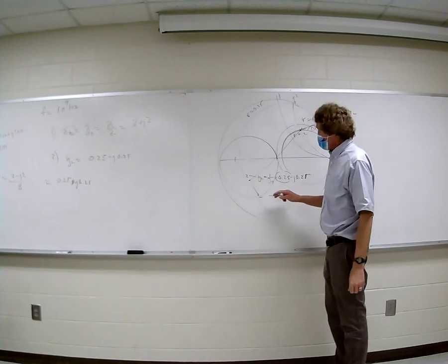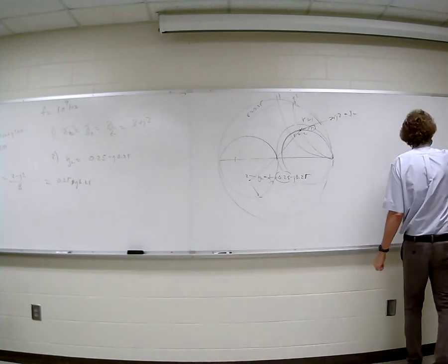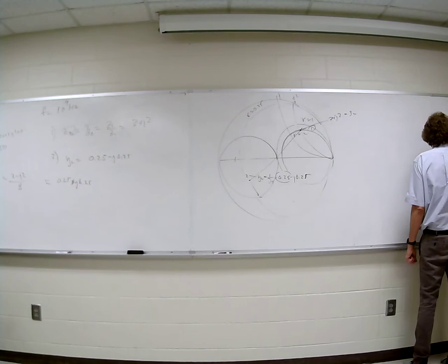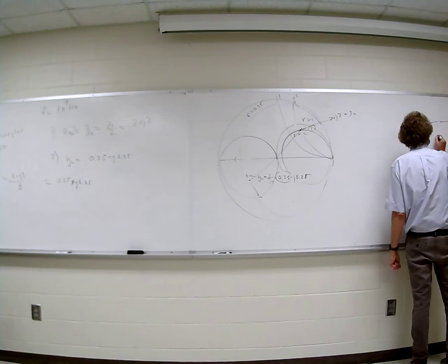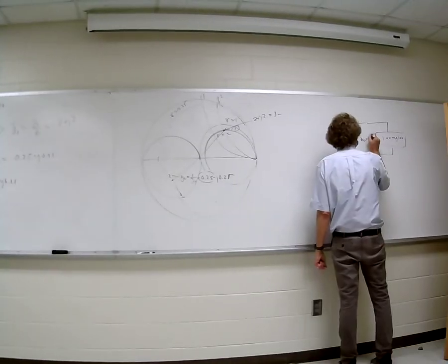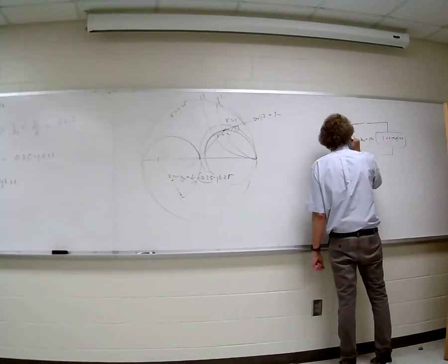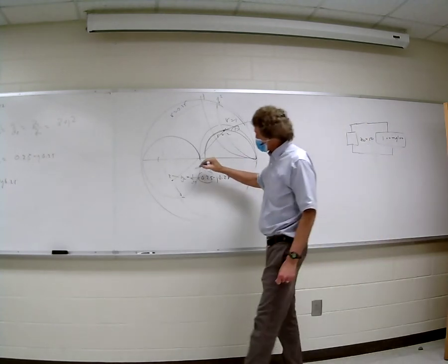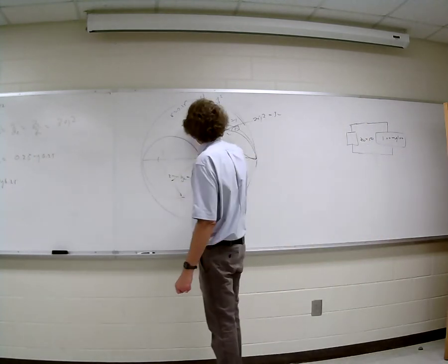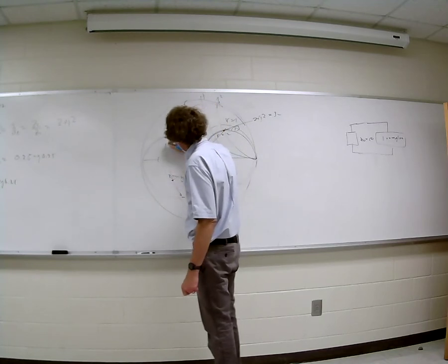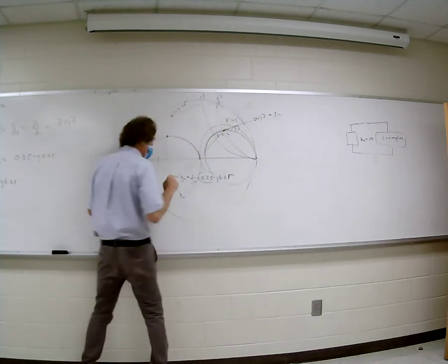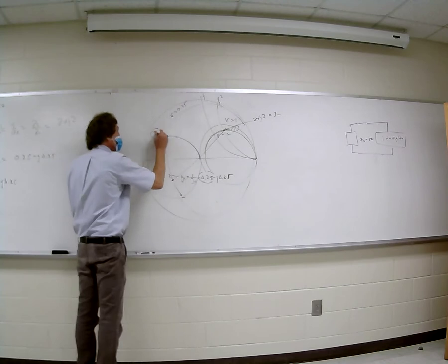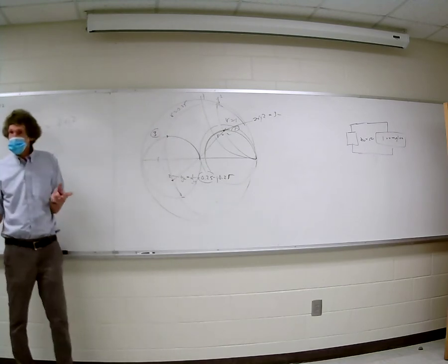So what I'm going to do, I didn't draw this, but this is my ZL, 100 plus j100. Here's my characteristic impedance, Z naught equal 50. The first component I'm going to add is parallel, and I'm going to just show you the admittance of it. So I'm going to go this way. Now, if you trace the 0.25 circle, you're going to come to this point, aren't you? This is where we're going to add it in. Do y'all agree with that?